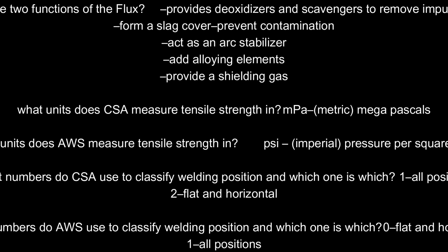Name 2 functions of the flux. Provides deoxidizers and scavengers to remove impurities, form a slag cover, prevent contamination, act as an arc stabilizer, add alloying elements, provide a shielding gas.